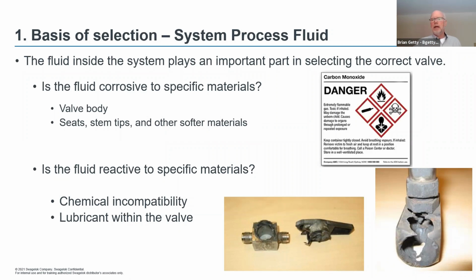But on this one, the person forgot to ask for special cleaning, and of course, what happened is the lubricant was non-compatible with a high concentration oxygen, and therefore we had a rapid burn, or a bit of an explosion and burn. Okay, so very, very important, you guys. Just got to keep that in mind.